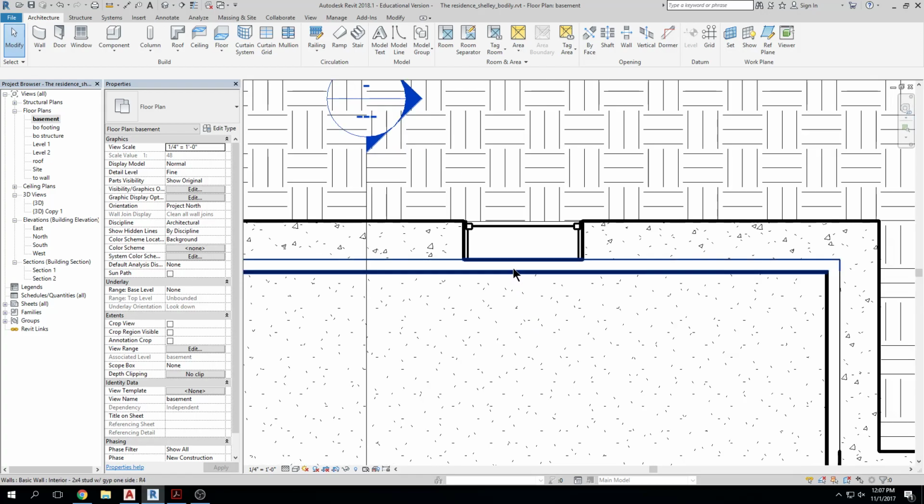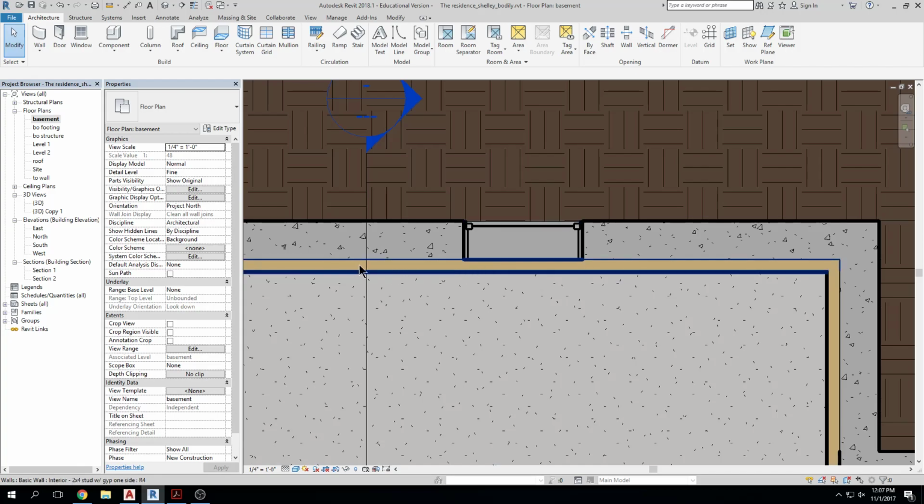The biggest pain in the neck here is that this wall goes full height and it doesn't allow an opening for the window, right? So if I do create 2 different walls, then I'm going to have to join them together to allow the window to show through this interior wall. So I have an extra step here. So number 1, I'm drawing my walls twice. I then have to join my walls together, okay? So I would go into modify.